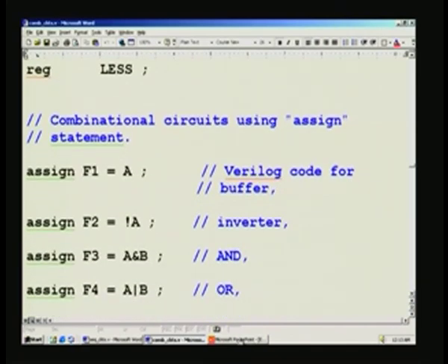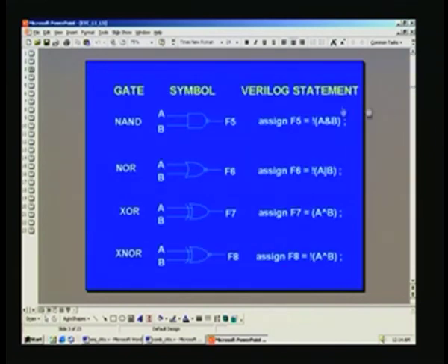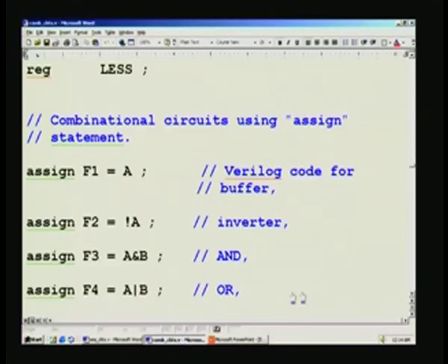So to start with, we had covered this earlier. We said how to implement a buffer using an assign statement. Precisely that's what we have put here, the statements appear here. That's why we said before that we will deal only with the core of the statements first, so that you get a quick grasp of those fundas, and then go on to more details which we have already seen, namely identification of module, how to put it together, then IOs, and then declaration of wire and reg.